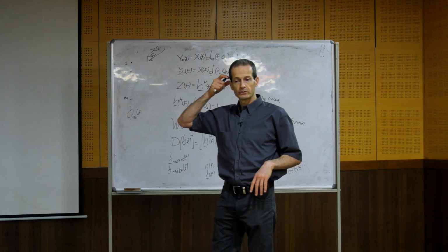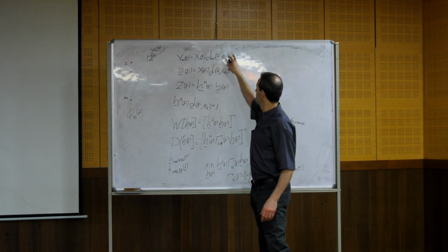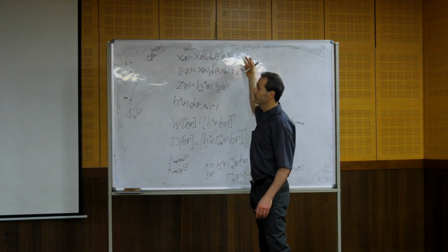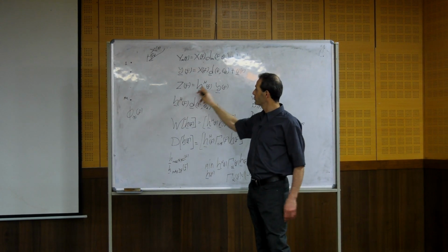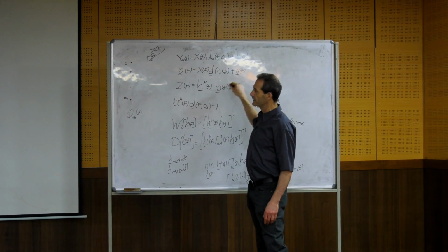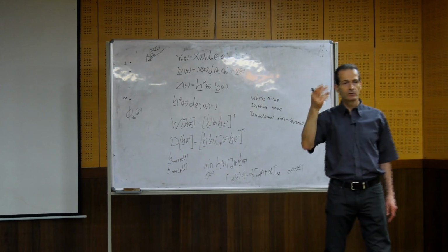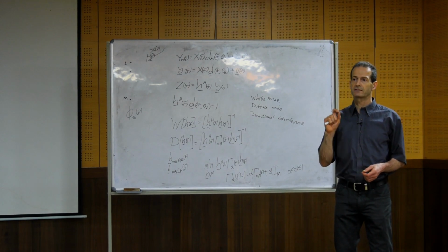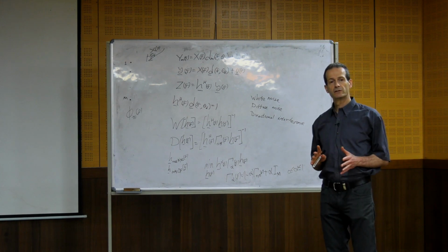These loudspeakers, combined with the background noise, will come back at the output of the beamformer. So they will appear here. So we have feedback. And if we use the gain and so on, it will distort, or we'll get some howling sounds, which we want to avoid.